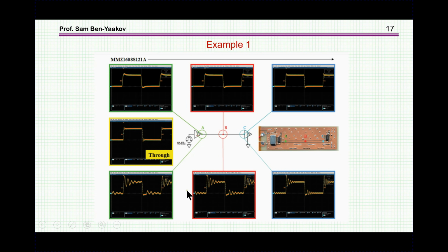Now, you can put a bead, here it is, and this bead is really improving it. You see that you don't see this spike, it's making it a low frequency rather than high frequency. There's no high frequency component here. And there's a slight difference. If you put a bead here, it doesn't help much because this line is now reacting. In fact, since this is generated, the source itself has the spike, then you better put it at the source, if the source is the reason for the interference. If the line is the reason for interference, then of course you need the bead here.